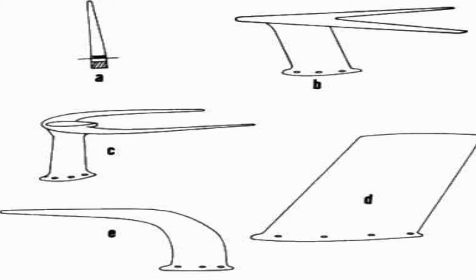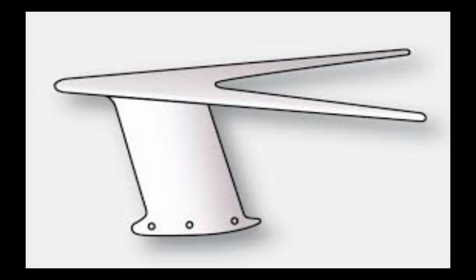Types of antennas. There are three basic types of antennas used in aviation: dipole antenna, Marconi antenna, and loop antenna. A common dipole antenna is the V-shaped VHF navigation antenna, known as the VOR antenna. Each arm of the V is 1/4 the wavelength, creating a half wavelength antenna which is fed in the center.